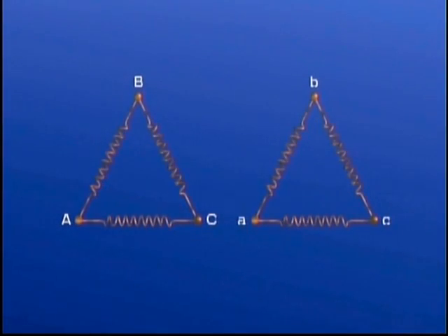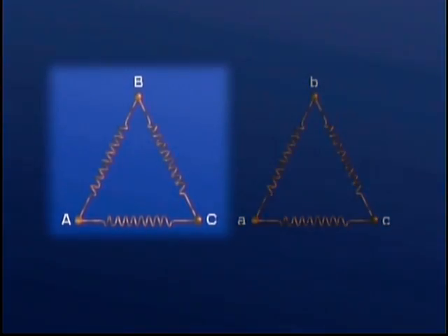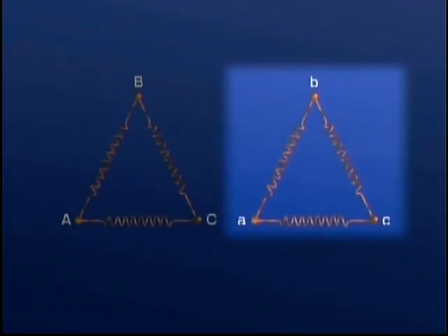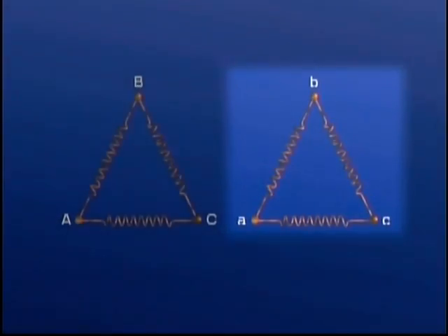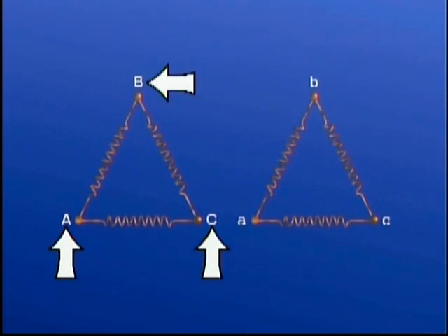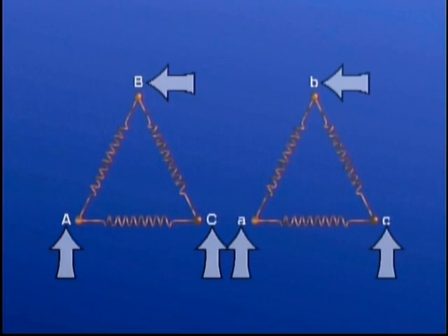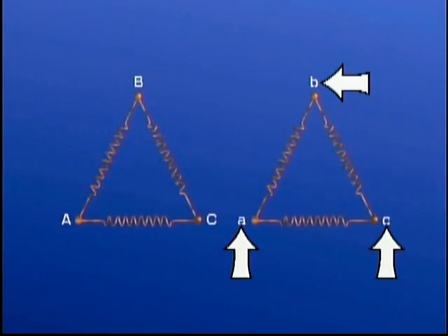Delta-delta connections are represented by two delta phasor diagrams. In this example, the phasor diagram illustrates the primary connections, and this phasor diagram represents the secondary connections. The uppercase letters A, B, and C on the primary phasor diagram illustrate connections to the primary phase wires of a delta system. The lowercase letters a, b, and c on the secondary phasor diagram illustrate the connections to the corresponding secondary distribution lines.